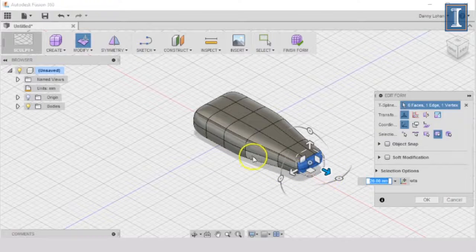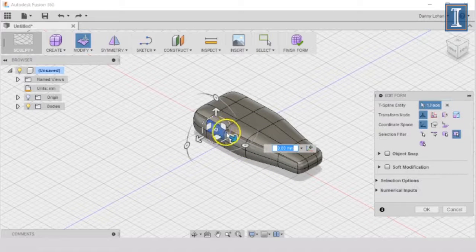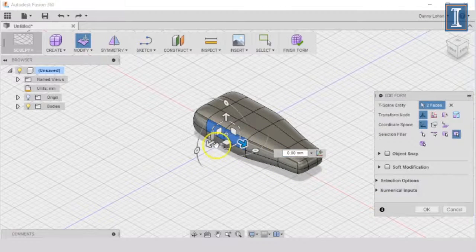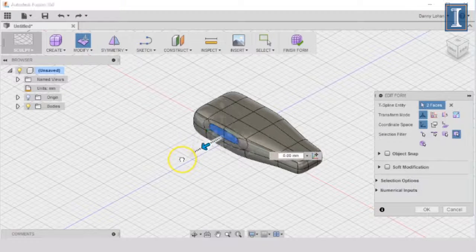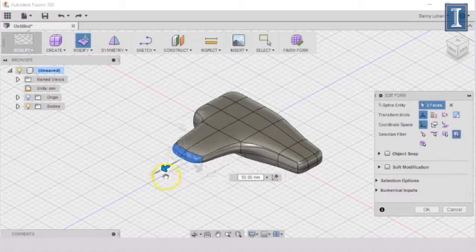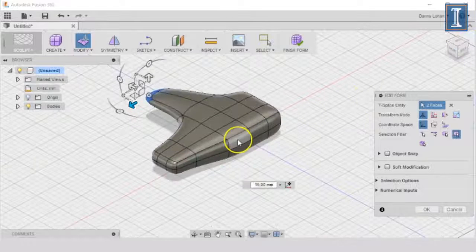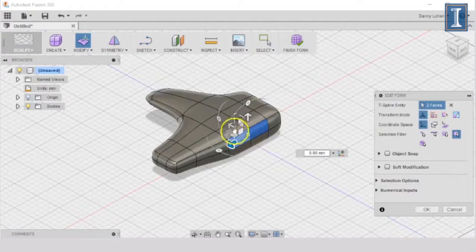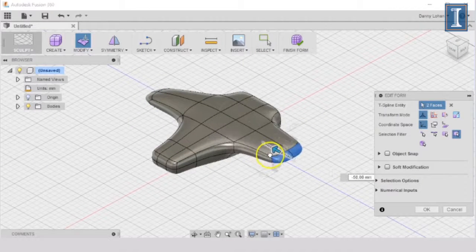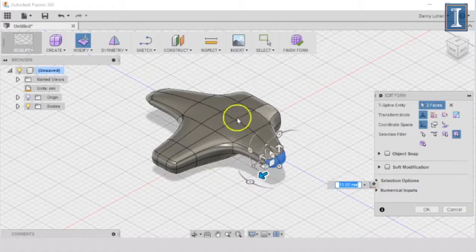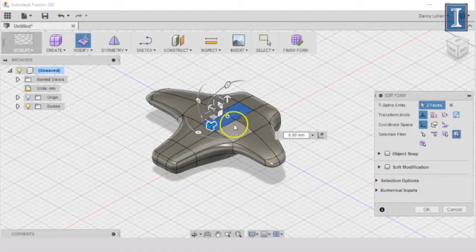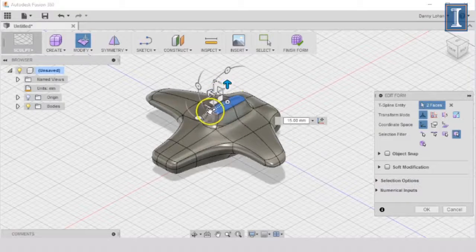In order to create the wings, we can select one of the surfaces or more and use the extrude function to pull that surface out, resize it, and reposition it. We can do the same on the other side for the second surface. By doing similar procedures, we can repeat this on all of the surfaces to create different features on the airplane.